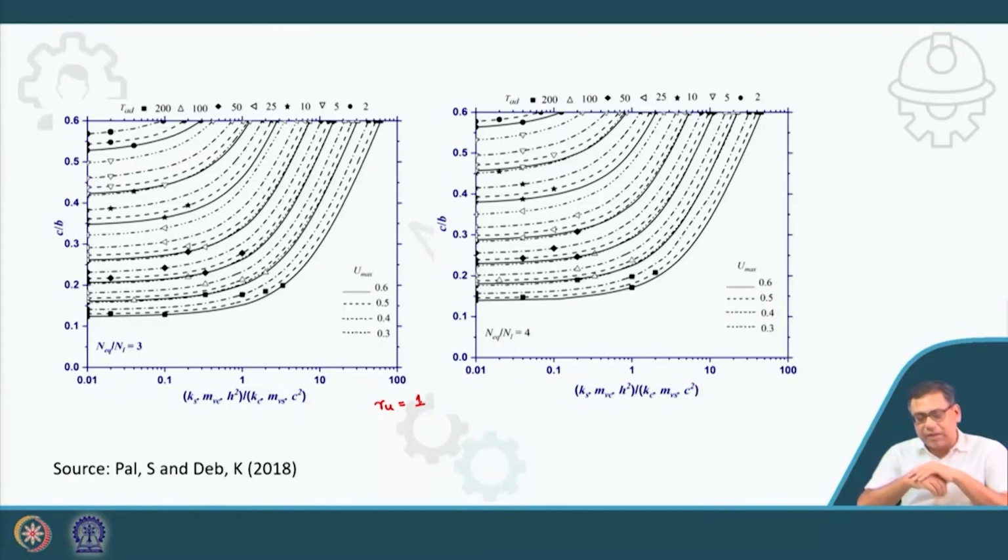So it has been observed that if your pore water pressure ratio is greater than 0.6, then there will be a stability issue in the stone column. So generally, that's why the maximum design RU value, or pore pressure ratio, is restricted to 0.6. Okay, that is one recommendation. So that means we will not design our structure or this ground considering more than 0.6 RU value.